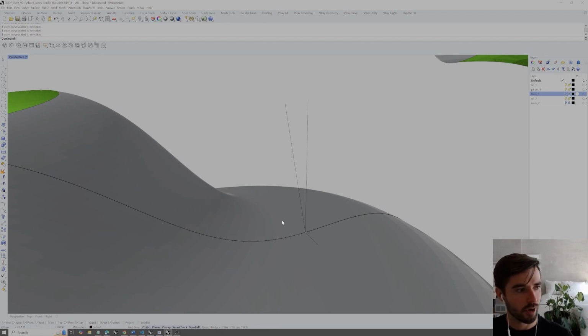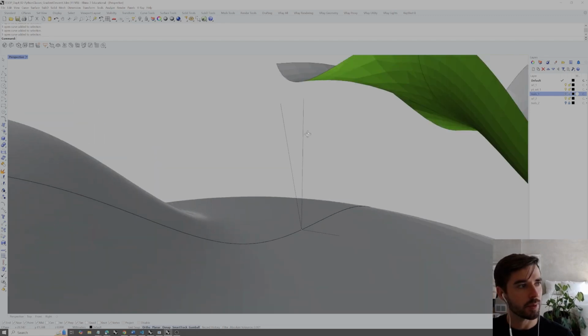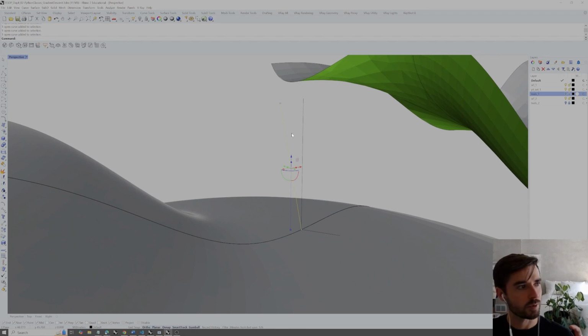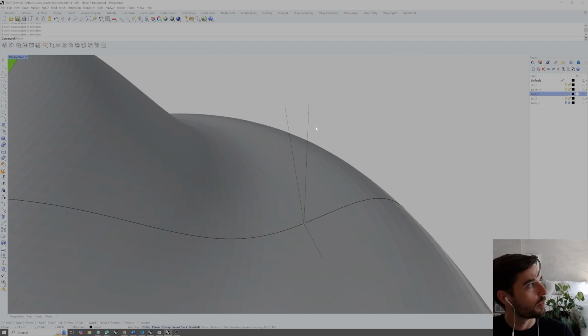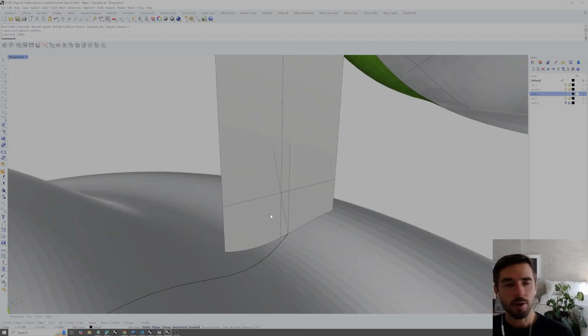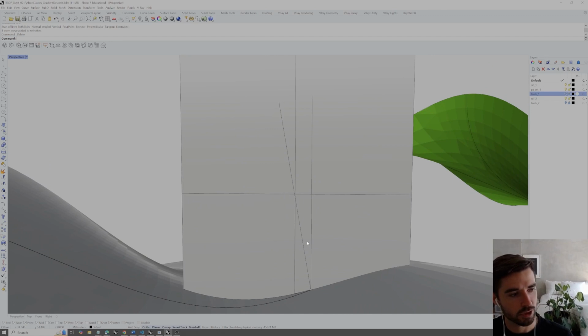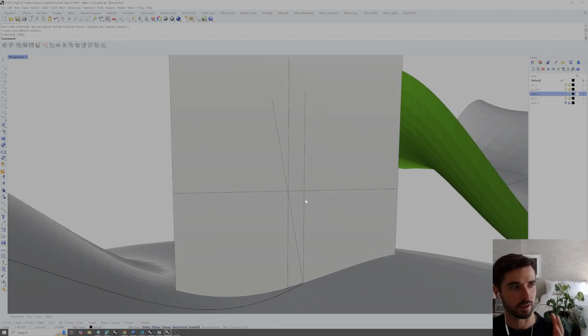So we know that we want that to be 90 degrees. Which plane does that occur on? Well, it's going to occur on the same plane as the difference between this vector and the z vector. So between these, a plane can be drawn out. So we'll do 3 point, and I'll draw out a plane here. So now the question is, what types of operations do we know that we can do with vectors in order to be able to extract that? So we have some relationship here that all three of these exist on some plane. We can draw some relationship between the z-axis then and our current normal in order to maybe get the slope that we're looking for here.